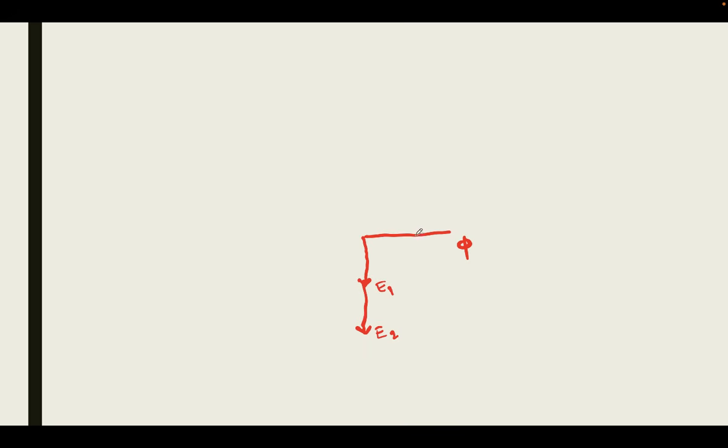Now, the current which causes this flux is already considered as Im, the magnetizing current, and the current which causes some loss in the transformer core is represented as IW. Now, at no load, we know the phasor sum of IW and Im is nothing but I naught. Up to this point, this is the phasor diagram of the transformer at no load.